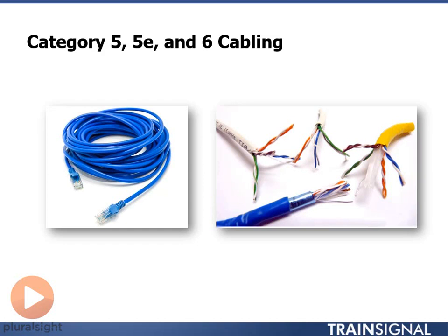electromagnetic intensive things. Like you don't want to run your Cat5 cable across a bunch of fluorescent lights. It will destroy your throughput. You have to use shielded twisted pair cable for that. You don't want to run your cable past some radio transmitter in your office. You need to use shielded pair for that. The idea, though, is to avoid all of these sources of highly electromagnetic interfering devices, which are typically devices that put out some large amount of power. Like I said, fluorescent lights are the biggest culprit that I know of.